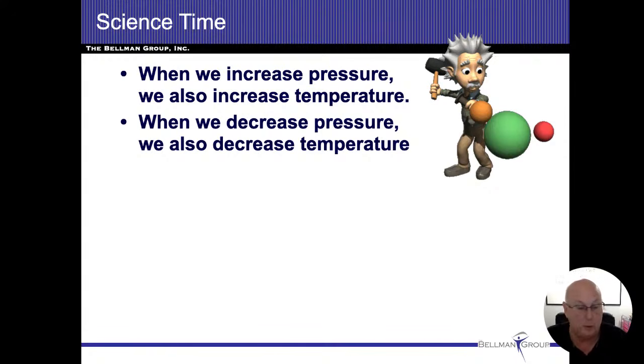And as it converts from a liquid to a gas, it has to absorb a tremendous amount of BTUs. And I need you to remember that part. It absorbs a tremendous amount of BTUs. And even on the other end, when we're discharging the heat, we're switching from a gas to a liquid. When we switch from a gas to a liquid, we're discharging a tremendous amount of BTUs.